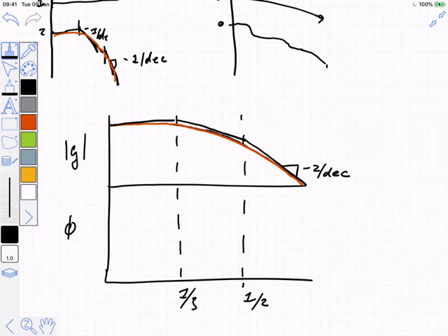And the phase is even kind of worse. It doesn't necessarily follow the same thing, but we see here that asymptote is -1 per decade. It starts there at 2. It starts out flat in the low frequency asymptote, and the two parts that are 100% guaranteed real, correct, are the very low frequency behavior and the very high frequency behavior, because how did we get the asymptotic behavior? We got it by taking the limits, right?